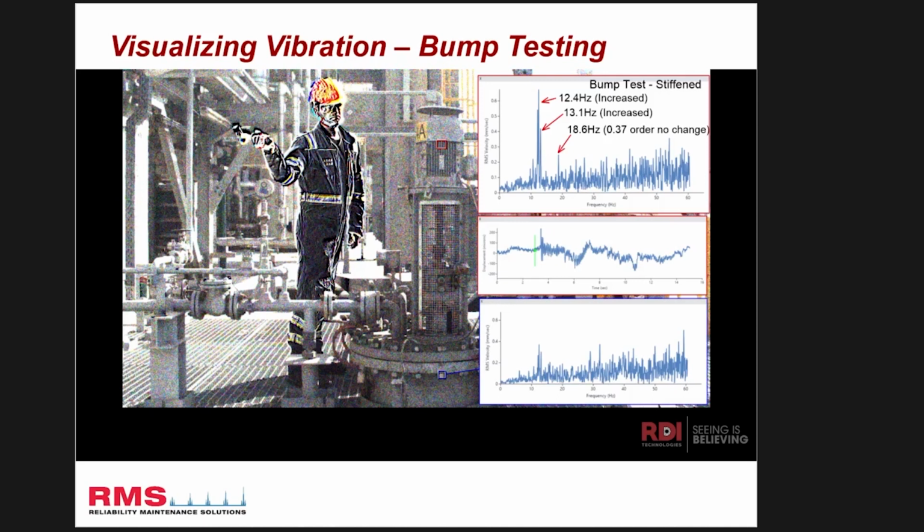Now, I don't know if you guys have ever been involved with this, but prior to the camera, and even now, if there's something running, I've had to do this, oh, it was so embarrassing, on a conveyor with an overhang, and the only way we can do it is called negative averaging, where we put an accelerometer on there, and you set your instrument up for negative averaging, which is going to take away the running, like exactly what you said.